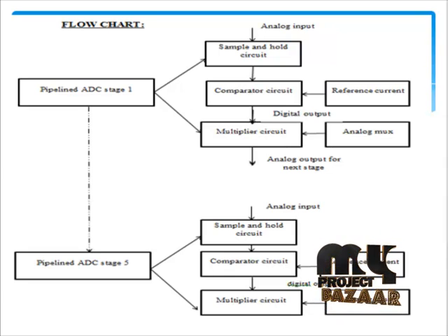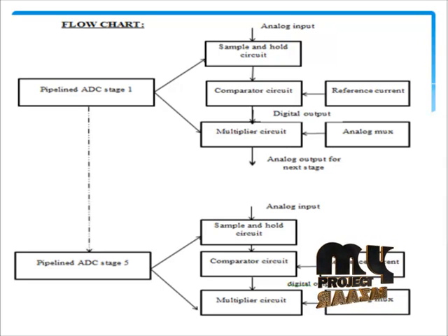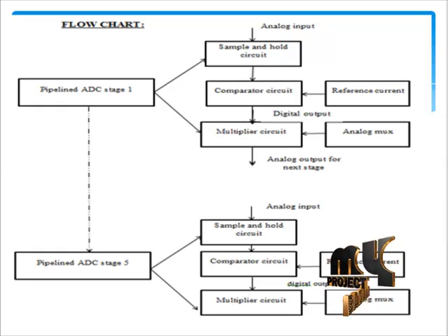The reference current and voltage are dedicated to calibration, with capacitor size set by matching limitation, noise limitation and power consumption. Additionally, the proposed partial non-overlapping clocking increases the residue bandwidth requirement in the amplifiers.